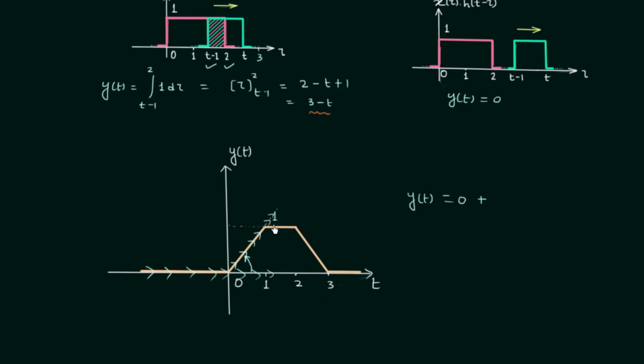It will become like this. And when you take the upward turn, you need to write down the magnitude of the slope. The slope magnitude you can calculate. It is 1 divided by 1. So the magnitude is 1, and the ramp signal will be rt minus 0 because the line is passing through 0. And once we have t equal to 1, again the signal will take a turn, but this time the turn is downward, and the flow of the signal will become like this. For a downward turn, we take the negative sign, and again we are required to write down the magnitude of the slope. These two angles are same, so the slope will also remain same, 1, and the ramp signal will be rt minus 1 because t is equal to 1 here.